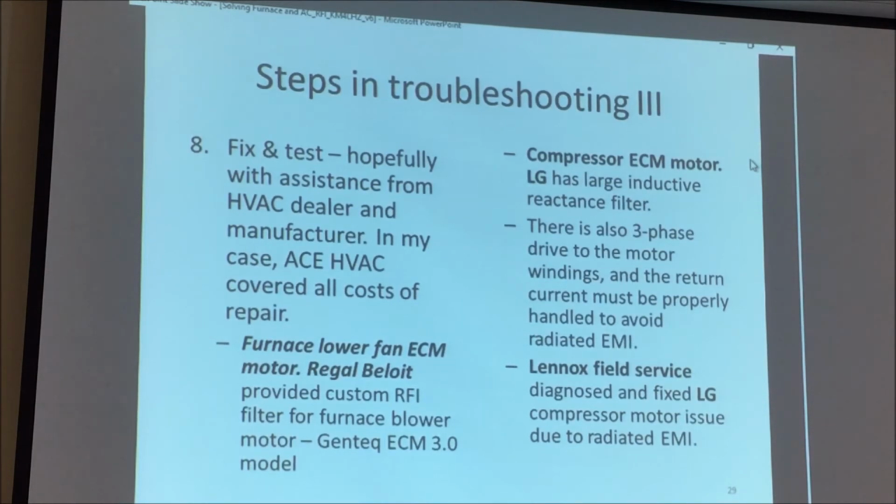But I did identify it, and what ultimately happened was that Regal Belvoir provided a custom RFI filter, which I'll show you, which ACE installed on the furnace blower, and that eliminated the conducted RFI.